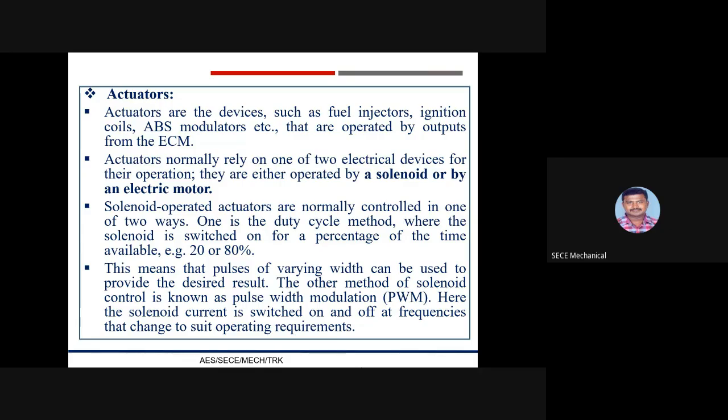So the actuators are an essential part of the electronic control system in passenger cars and commercial vehicles. It is their job to convert the electrical signals from the control unit into an action. Most actuators are electric motors or electromagnetic valves or devices. They adjust flaps, for example, regulate the flow of fluids, or actuate pumps to build up pressure. That means we can use these in braking and steering systems, for example.